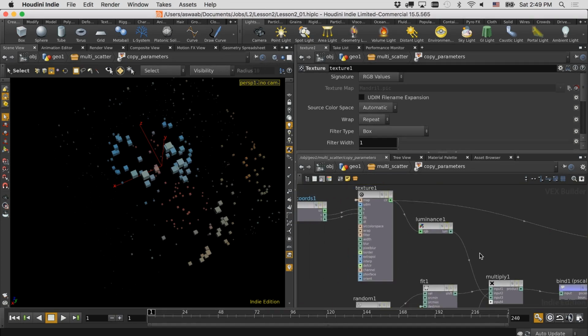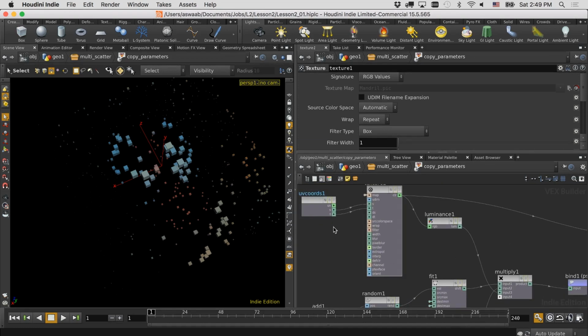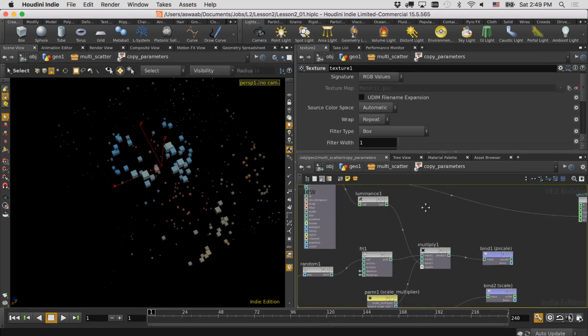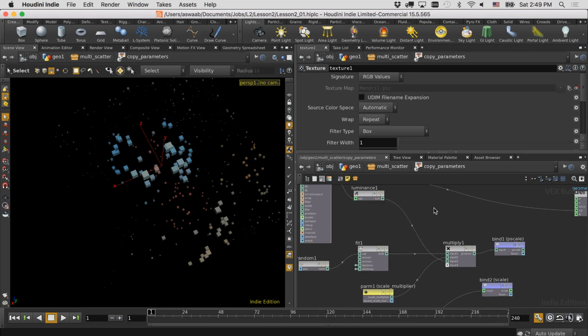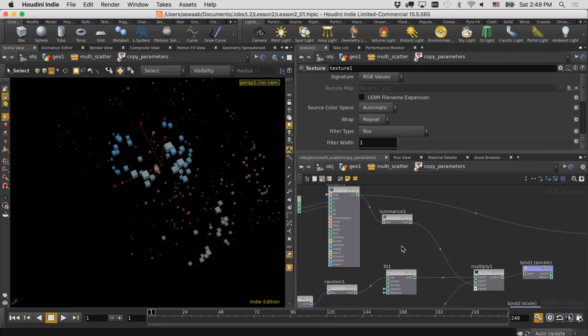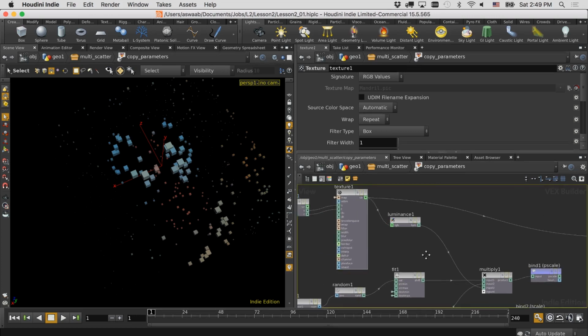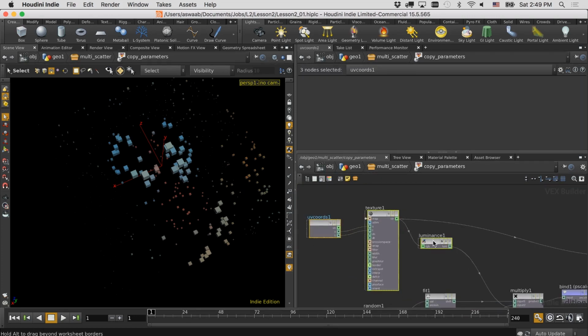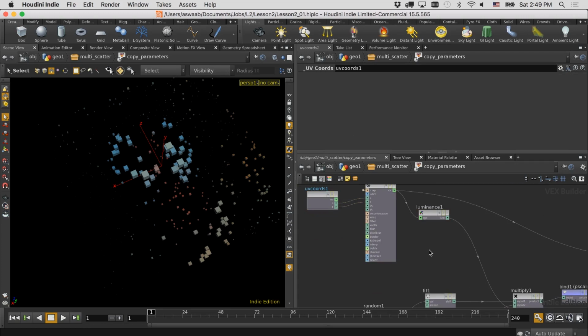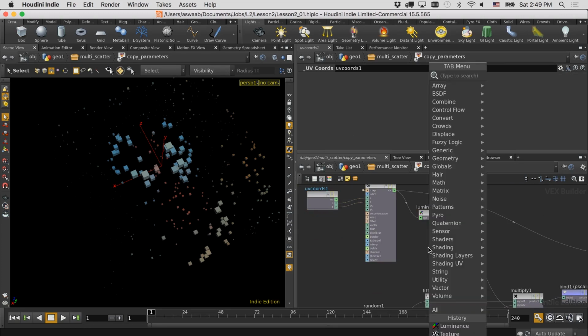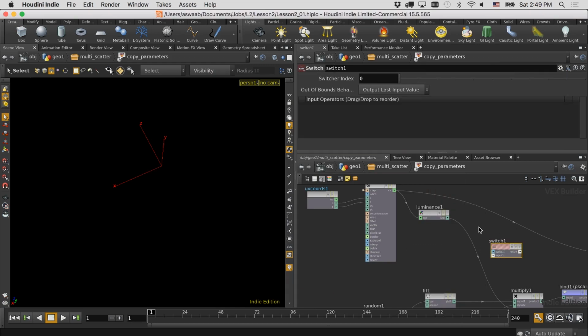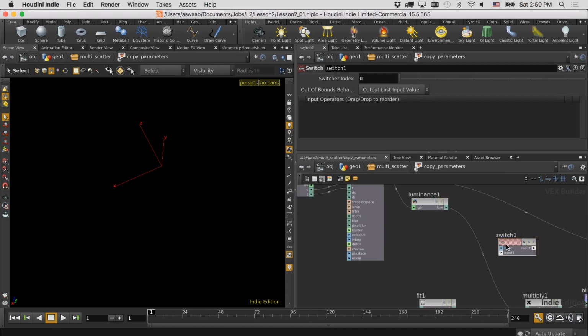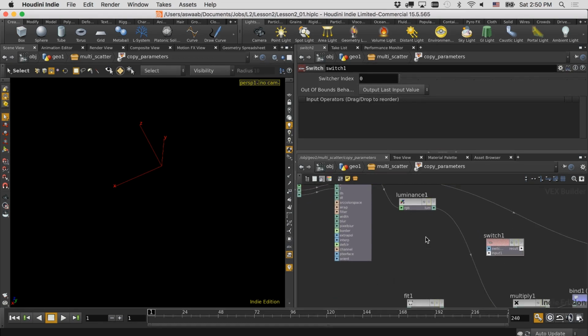And then we may just want to actually switch this on or off, in terms of just adding a button, like a use image button. So let's just do it this way. Let's just press tab and start typing the word switch. So this is going to give us an error right away, and this is a switch just like we used previously. And all we need to do is create a parameter here.